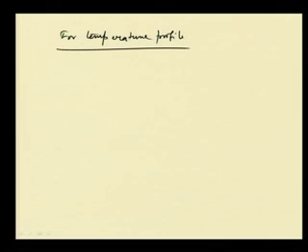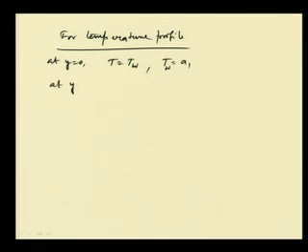Similarly, for temperature, we can write at y equals 0, T is equal to T w, and then T w is equal to A 2. And at y equals delta, T is equal to T infinity.